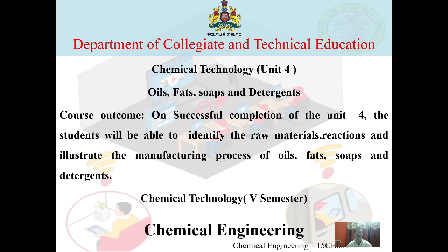These impurities are removed by vacuum distillation. After vacuum distillation, the glycerine vaporizes, and these vapors are taken out and fed to a condenser to condense the glycerine vapors, which gives us yellow glycerine of about 99%. This yellow glycerine is then converted into water white glycerine by bleaching it with activated carbon.